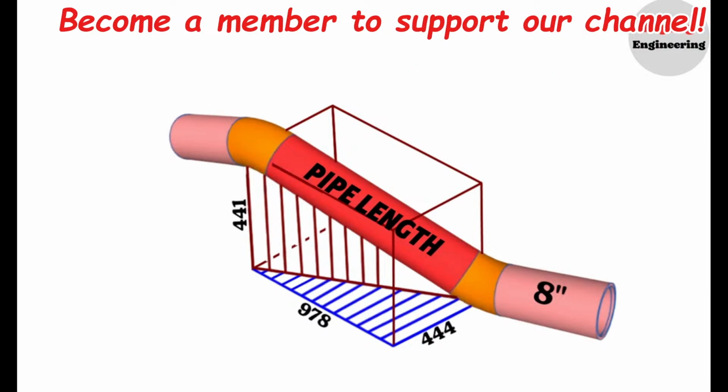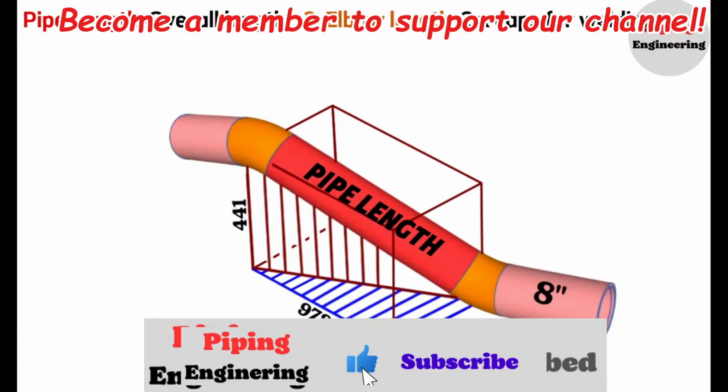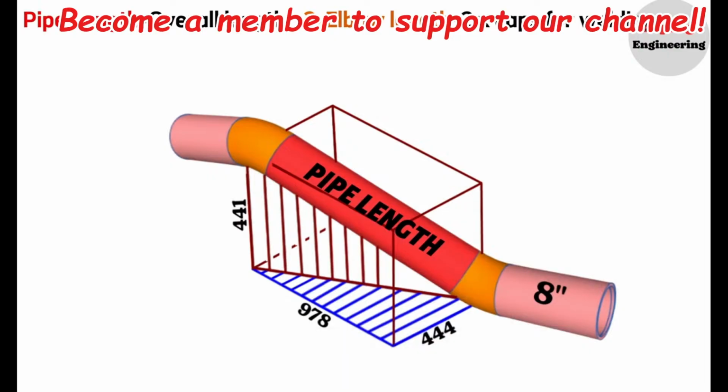The formula can be expressed as pipe length equals overall length minus 2 times elbow length minus 2 times gaps for welding. We will perform all these calculations step by step on this 8-inch pipeline section. Let's denote the overall length, or the center-to-center distance between the elbows, as L.